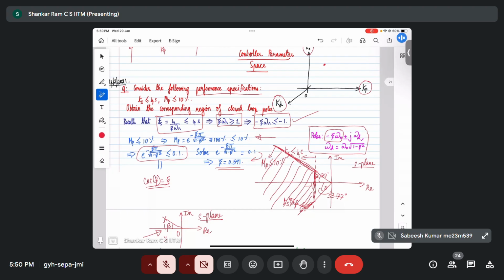That makes some presupposed assumptions. If you derive the closed loop transfer function and take the dominant dynamics, you will see that effect. Ultimately, the denominator polynomial of a dominant second order system is s squared plus 2 zeta omega n s plus omega n squared.